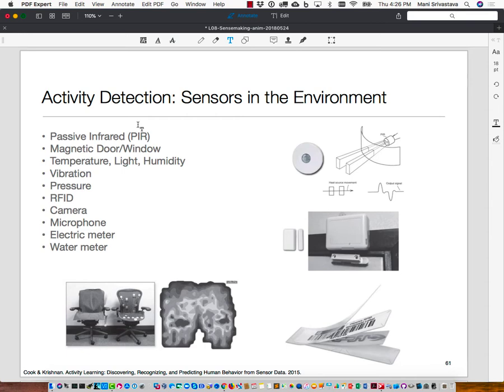light coming from something. So that's what PIR sensors do. They look for IR emissions, which is basically what body heat is. And in particular, they look for changes in it. That's why they're called motion detectors. The reason they look for changes is so that you can subtract out static heat sources, the sun and stuff like that. Okay, so you look for those changes. Magnetic door and window sensors are super simple sensors. I'll show a picture of them out here. Again, I'm sure you would have seen these things. Basically, when the door closes, the magnet comes close to the sensor, and vice versa.